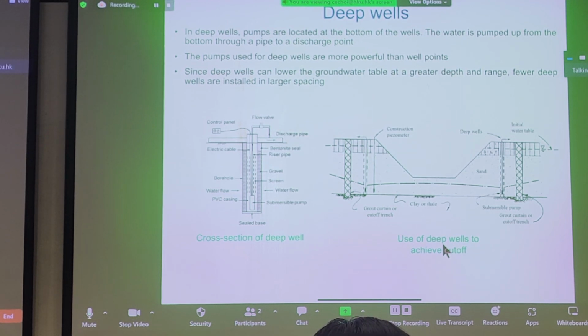For sump pumps, you're probably just looking at a temporary alleviation of the groundwater table so you can get some ground improvement done quickly. More often than not, if you don't need to sink deep wells, you probably won't, because it's expensive to drill a borehole into the ground.